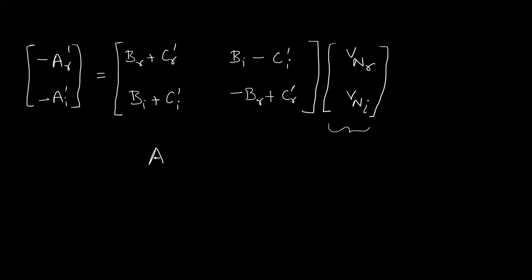So this is very similar to the AX equal to B format, and as we saw in the previous lecture, we can solve this equation for X as A inverse B. Without doing the inverse of the A matrix, we can solve it by means of LU decomposition and backward forward substitution. So here we can solve for the real and imaginary values of the voltage. So that is the algorithm for this linear load flow. So in the next video we will see an example. By means of an example we can understand it.